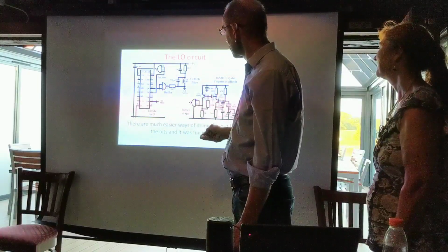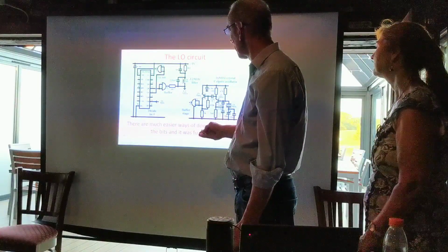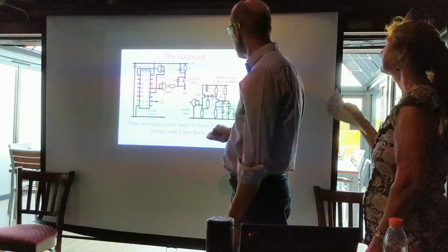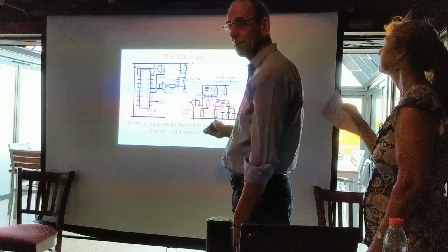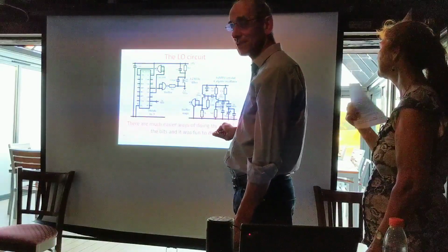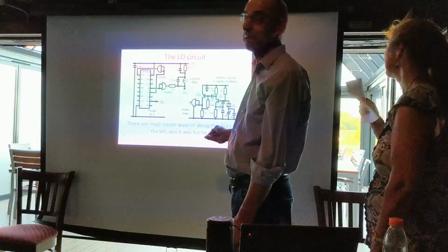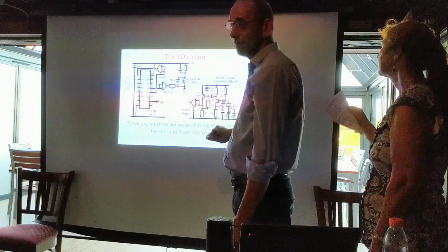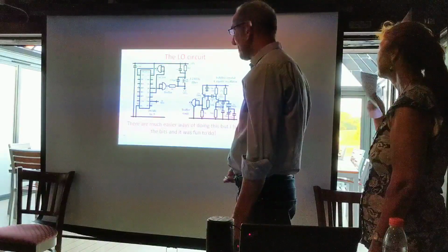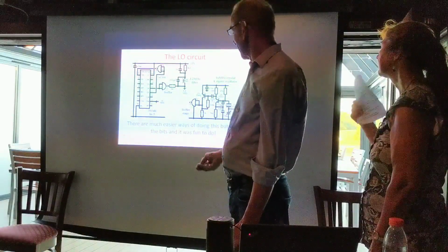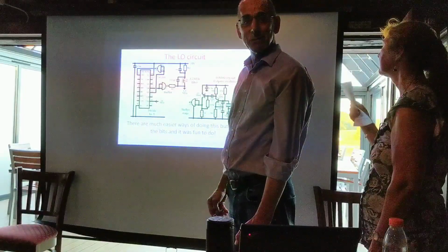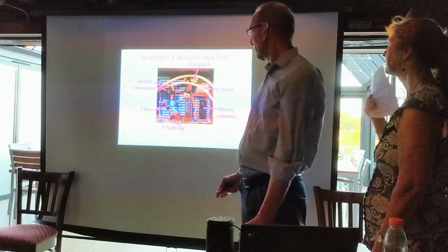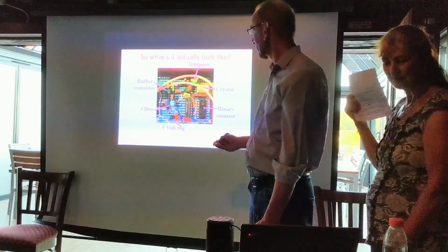There's a little bit of logic around it because the signal needs to be the other way up to operate the reset. The output from that, QB, as Sue said earlier, I'm feeding into, oh look what this is, your bog standard parallel tuned circuit at 3.2 megahertz, to nicely get rid of everything else. And that actually goes to a buffer, but I haven't bothered to draw that on here. Now, there's massively easier ways of doing this, but boy, it was great fun, and I had all the bits, so why not? And that's what it actually looks like when it's built up on a bit of old board. Thank you, junk sale.